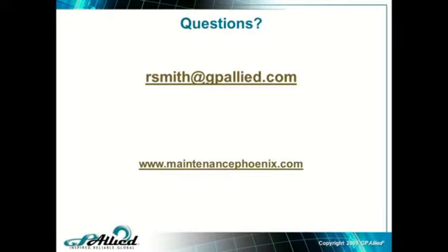All right, here's another one that just came in. They're saying that you showed the equipment taxonomy, which is defined in the ISO 14224, but can that be purchased in a format ready for upload to SAP? Are you aware of that? Yes. But what you have to do is take the equipment taxonomy, look at the equipment hierarchy, and match it as close as you can to what you need. So you can drill down from the highest level.